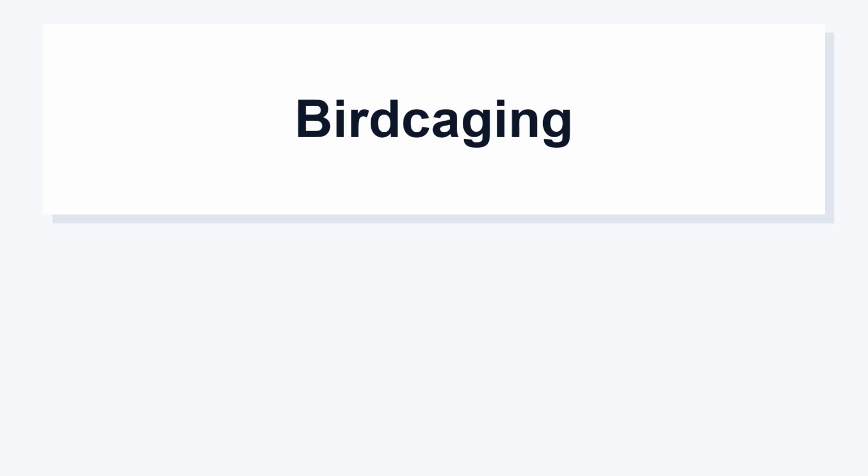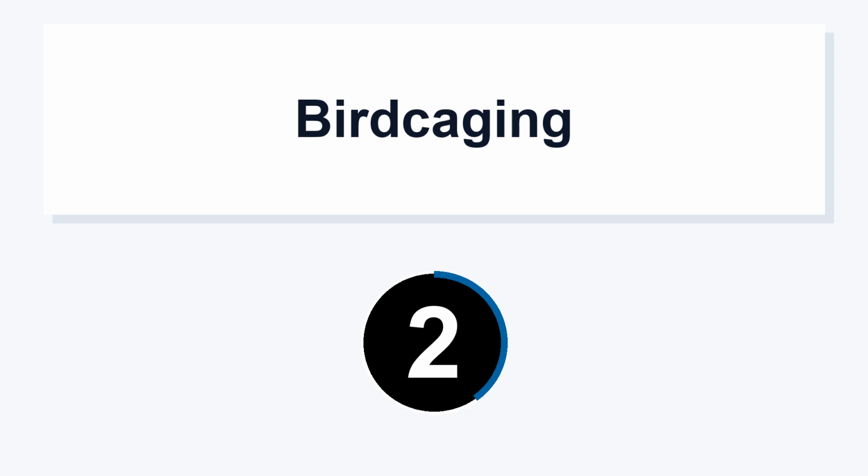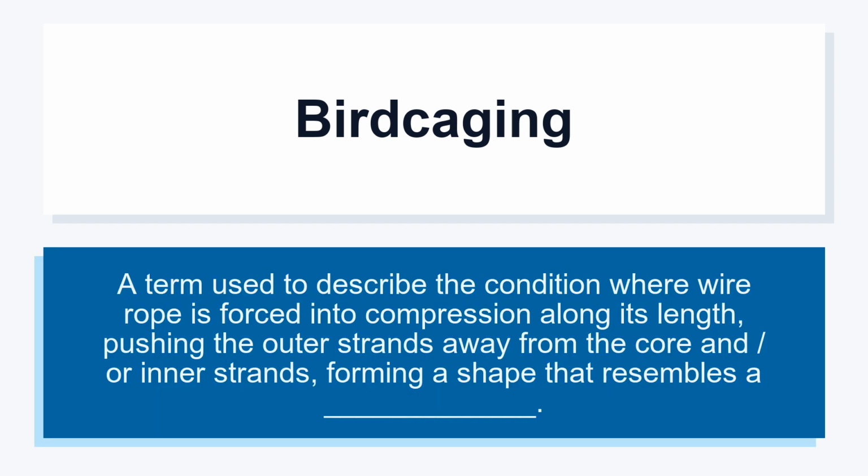Birdcaging. A term used to describe the condition where wire rope is forced into compression along its length, pushing the outer strands away from the core and/or inner strands, forming a shape that resembles a ______.